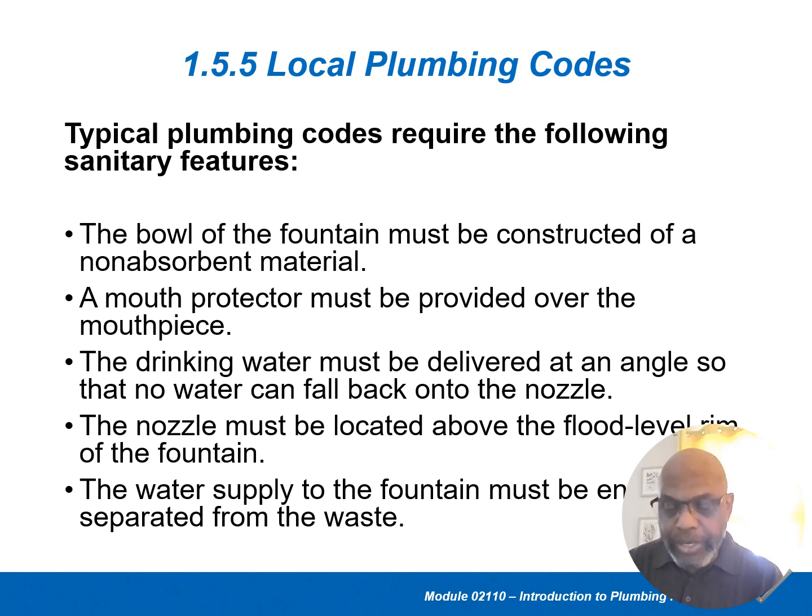How we pipe in toilets, showers, anything that has water coming into any fixture should have a drain on it to get rid of the waste. And there are specific codes for everything that ties into the piping, the size of it, the type of fittings to use to make sure that you are getting rid of the water correctly. As a matter of fact, even the pitch of the pipe, the direction it is going, and the angle that it is at matters.